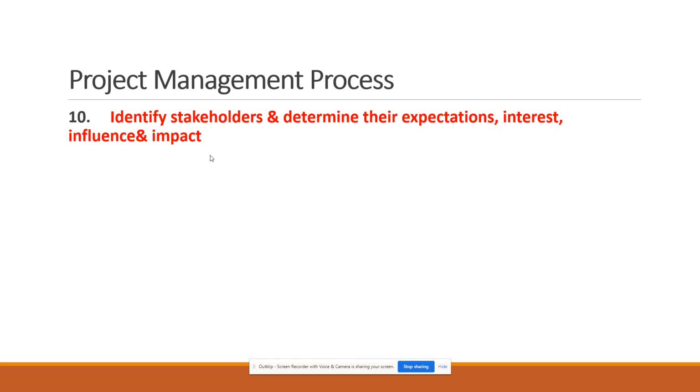And if you are doing the project where there are houses, and if there is any noise pollution or air pollution, or if any pollution happens, and the people complain to the agencies, then you will get the fine. So you have to identify what are the things coming in your project and who will be the expected stakeholders for approval. These are the things you have to get.